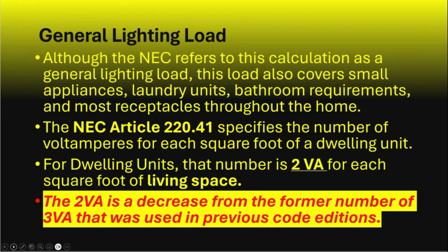And if you look in the 2026, there is a section that speaks regarding determining the calculated load for branch circuits. And when using that calculation, you still calculate it at 3 volt amperes per square foot.